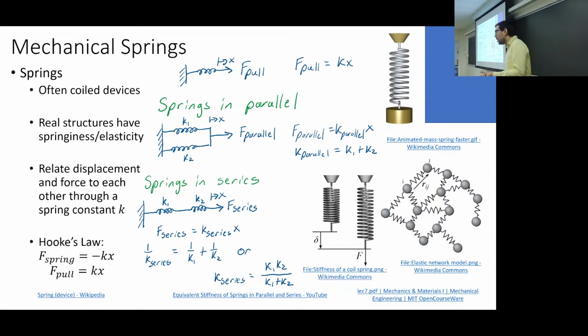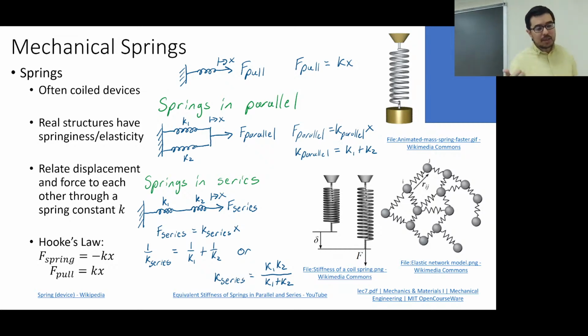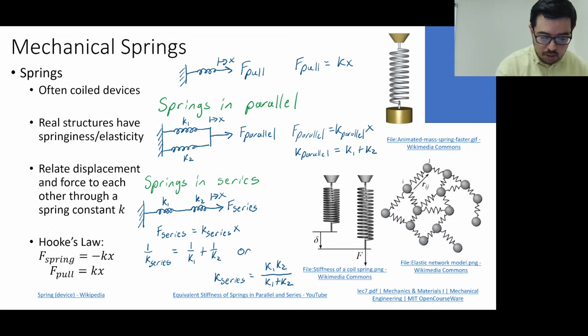Now if they're the same spring constant and everything, and it's a symmetric loading, then both springs will be experiencing the same amount of force. But the boundary condition essentially is that displacement is the same. Maybe I'll just write that here. Okay, so in springs in parallel, we have same displacement. Oh, that looks bad.